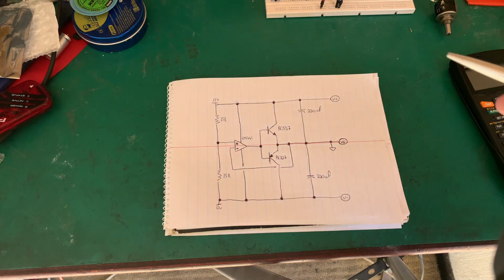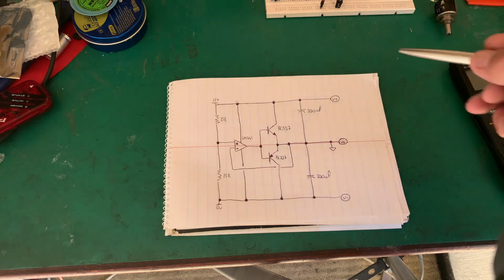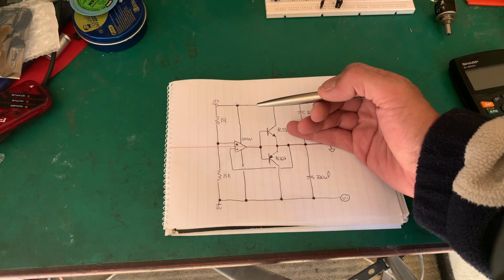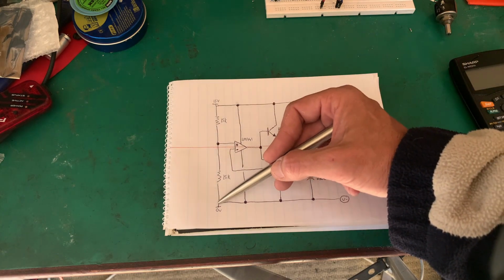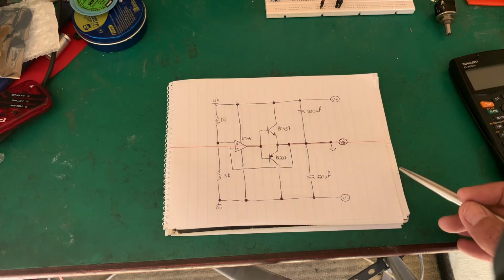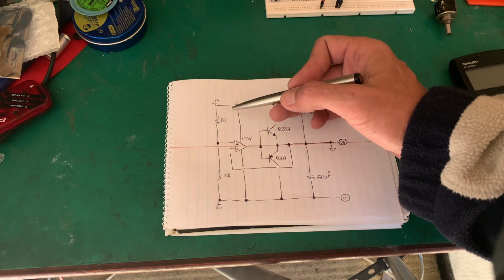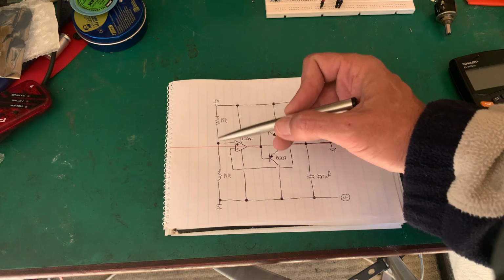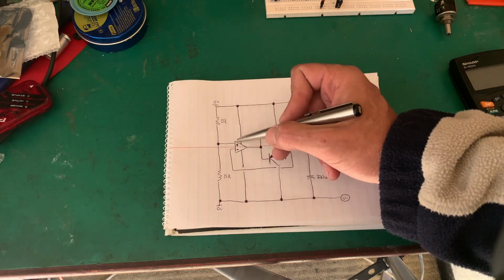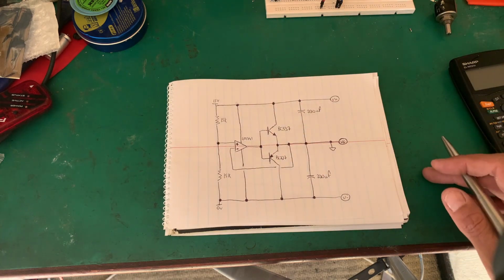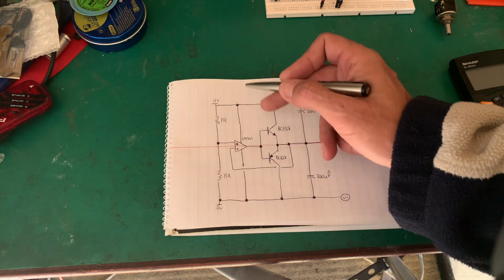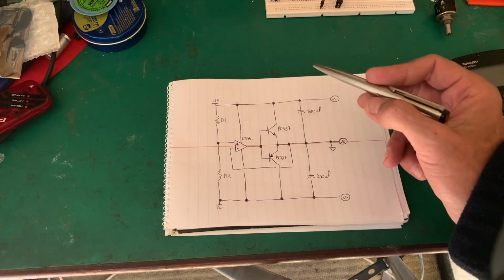We spoke about split rail, and I've just made a little circuit to give you a split rail if you don't have a center tap transformer and you follow a few rules. Let's say we have an input supply of 15 volts rail to rail. Well, if we put a 15K and a 15K, then they must be identical there, and we take it to the non-inverting input of the op-amp. We power our op-amp off the 15 and 0 volt.